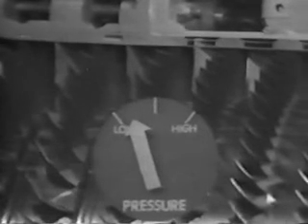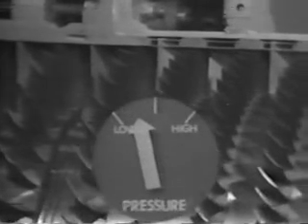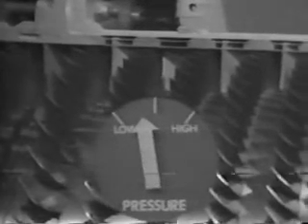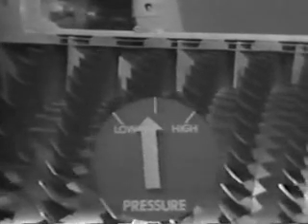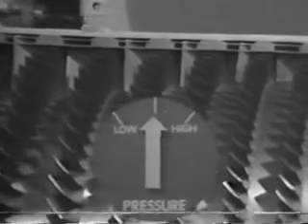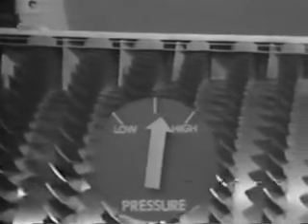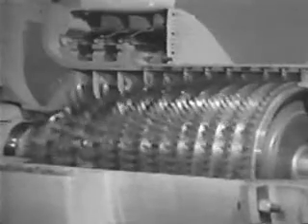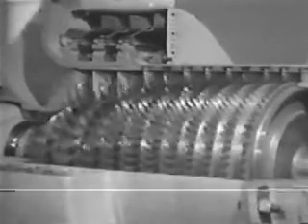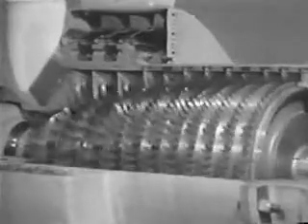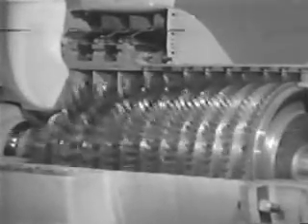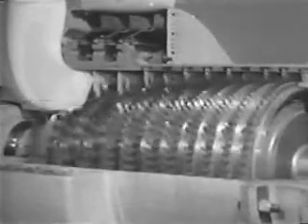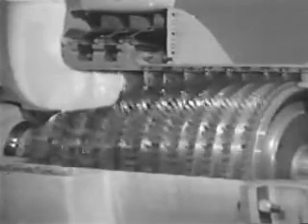While the velocity of air remains almost steady, the pressure is increasing as it passes through each stage. Each stage multiplies the pressure obtained from the preceding stage. A very small pressure in the first stages quickly becomes a very high pressure by the last stage. Remember that the air path decreases in size along the compressor's length. This permits the compressor stages to maintain the pressure passed along from the previous stage.